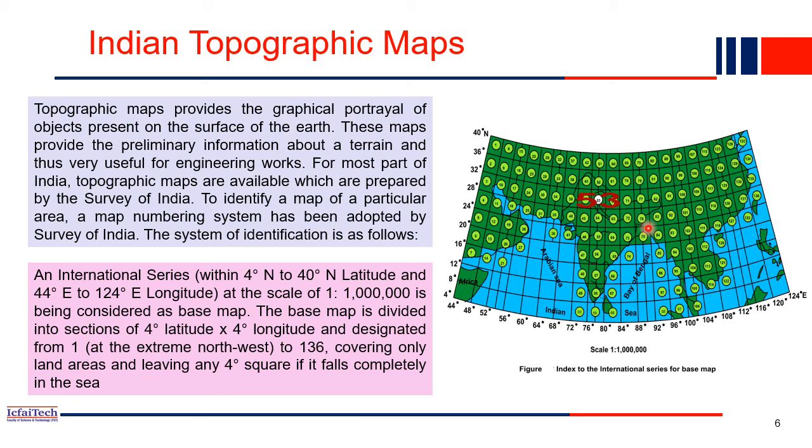With the reference of this Buddha statue, if you want to locate the entire Hussain Sagar lake area, or any nearby gardens, that can be done with reference to the statue's known latitude and longitude. So we divide this entire area into multiple control points using triangulation. We establish a third point using these two control points, and from this third point we again take the triangulation and establish one more point. Like that, the entire big area is divided into small parts.